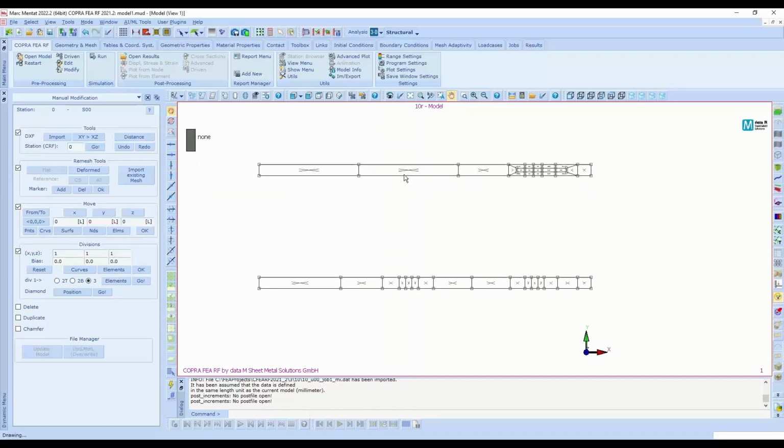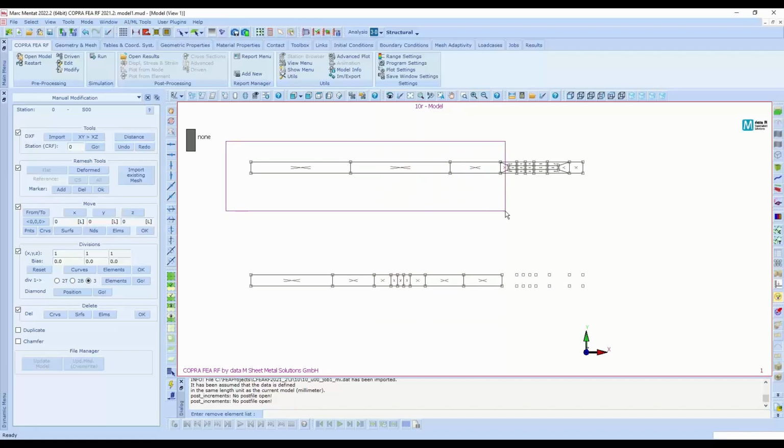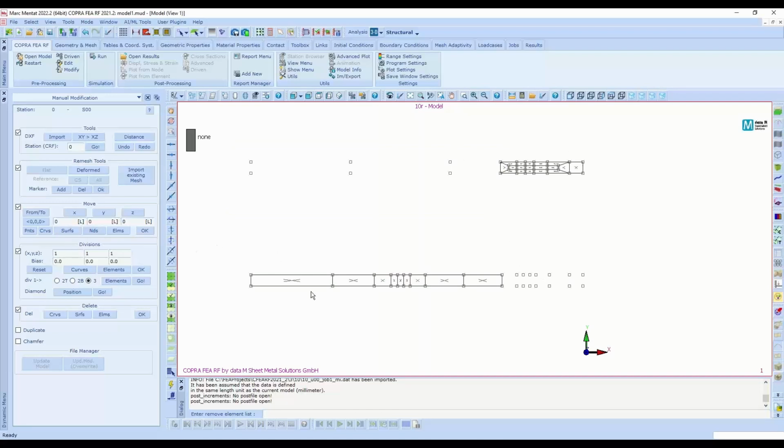So now close it. And what I'm going to do is delete elements from my actual mesh and from the top mesh and join together. So now I have to move the top one to the bottom, not the bottom one to the top, because otherwise when we start the simulation it could be a mess. So we have to be careful always, as usual. We have to think.